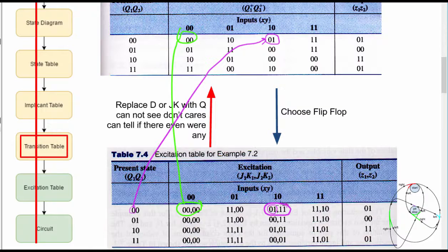All right, now let's look at this one. This is J2 and K2. It's going to influence Q2 by doing what? Well, 1, 1 stands for toggle. So it's going to take that 1 and toggle it to a 1. Let's try another one. Let's try this one right here. This is going to take this 1 right here and toggle it to what? A 0. The other direction is something we did at the end of chapter 6.